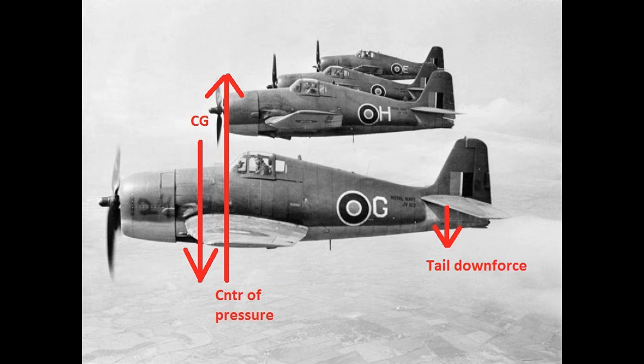Now we speed the plane up to 240 miles per hour indicated. Now any pilot, or even most simulator pilots, will tell you that as you speed up to 240 miles per hour, you're going to need to add a bit of nose-down trim. As a general rule in subsonic flying, with all other things equal, the faster you go in a plane, the more nose-down trim you're going to need. Why is this? Well, the main reason is that at higher speeds, the tail produces more downforce for a given angle of attack, thus forcing the nose up. So we counter that with nose-down trim.